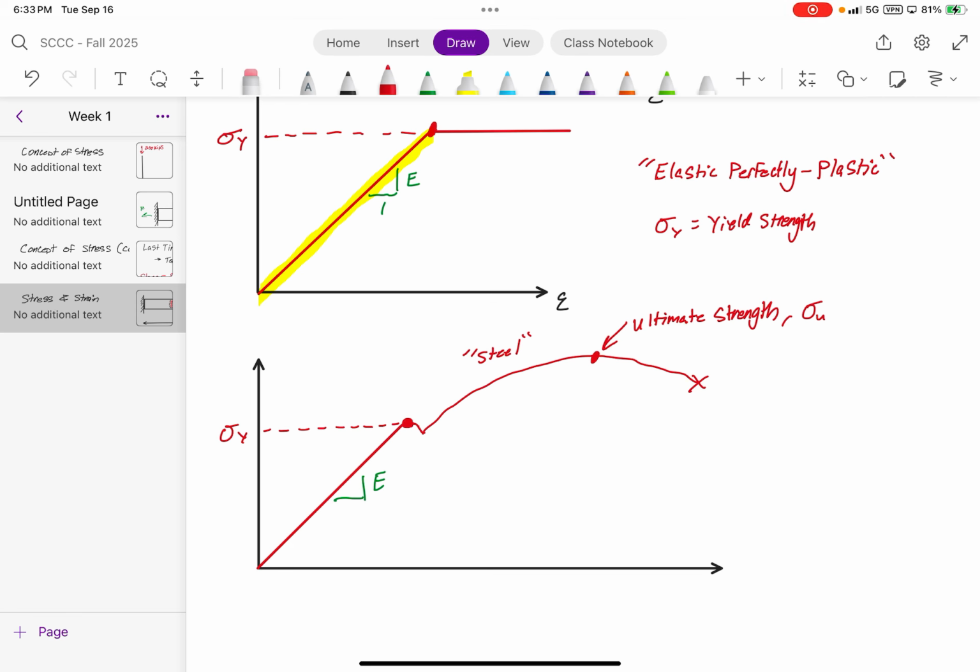So really when you're designing really large scale members, the deformations are really important. So you usually try and stick with that elastic region, right? You don't want your 8-foot long beams deflecting too much, because then serviceability requirements really come into play. But if you've got a bolt, it's such a small cross section, it's not really going to contribute to any type of deformation, right?